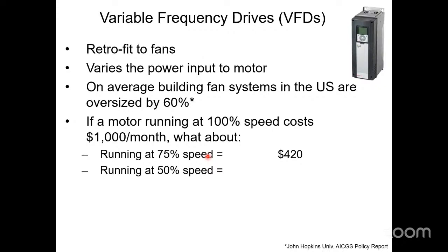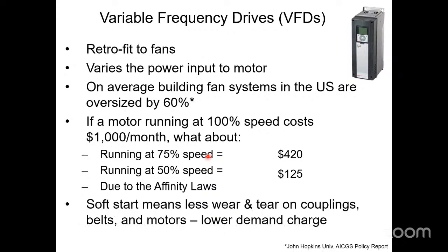If I cut the fan speed in half, it's obviously not 500 bucks because it's got to be less than 420. It's only 125 bucks to run it at half speed for this example. So you definitely want to be able to ramp these fans down. This is due to the fan laws, or if you're a pump manufacturer, you call it the pump laws. And if you are Switzerland trying to be nice to the fan and the pump guys, you call it the affinity laws. Plus, it sounds like superhero stuff, so it's pretty cool.